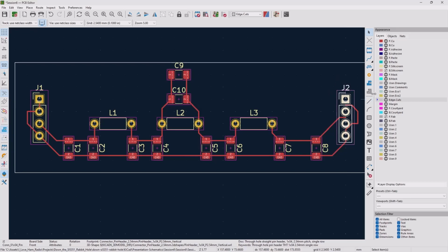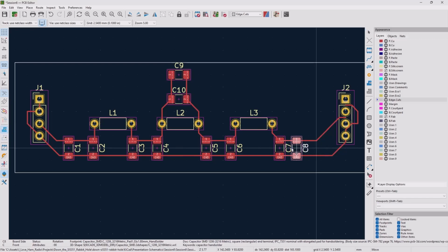That's it. I would tighten up C7 and C8 and bring everything left. Okay. Bring C7 left underneath the pin for L3, where it's just vertical, kind of like L1, C2, and C3. That's a good look. Now I'll bring C8 in again. Well, C8's in a good position. Then bring J2 in and reconnect L3, C7. Okay, J2 in. Or you mean JC? Oh, J2 in. Yeah.